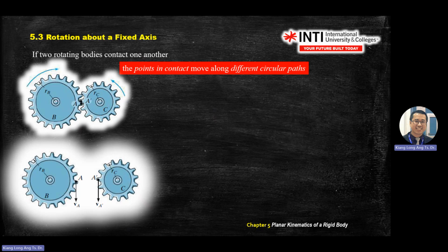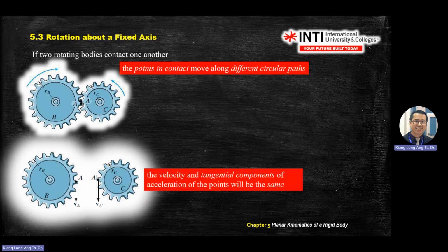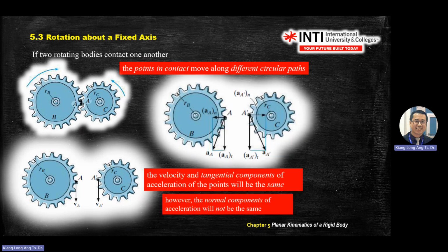Interest point A, this one is circular. For circular motion, you are only interested in velocity. Velocity is always tangent to the circle. You just go to the point, draw a 90-degree line or tangent line at that interest point. Then the same with C. CA goes up, goes down, right? Then the rest you solve accordingly.